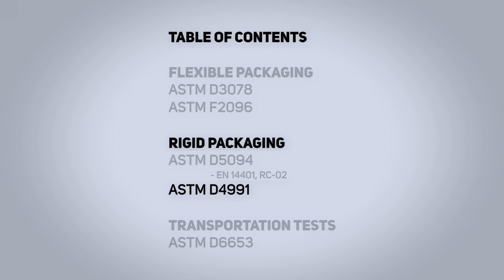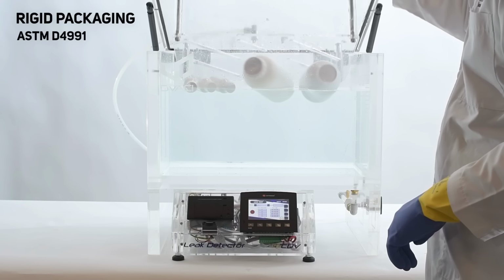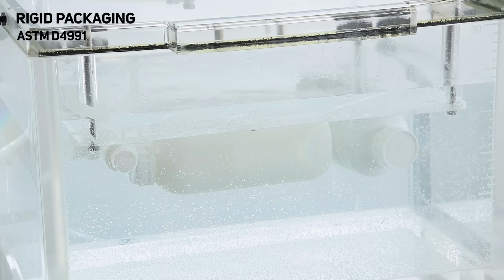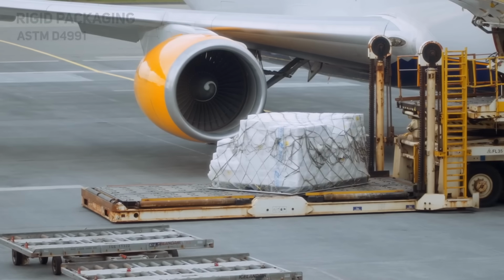ASTM D4991 allows for validating the airtightness of empty rigid containers via a vacuum immersion test, looking for bubbles to identify sealing integrity issues. This standard is especially useful for containers holding hazardous materials intended for air transport.